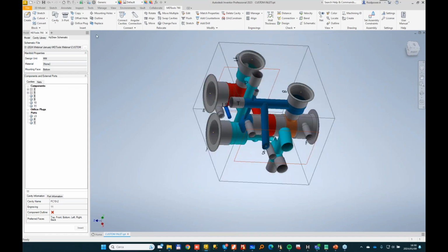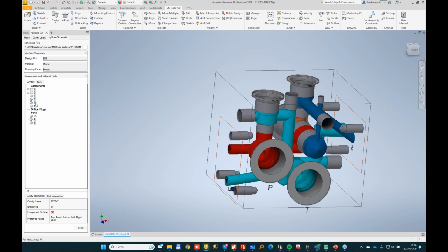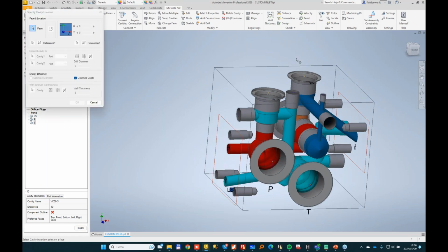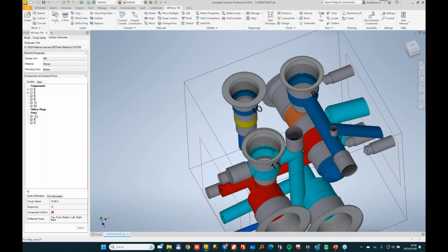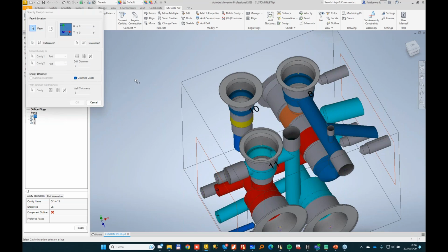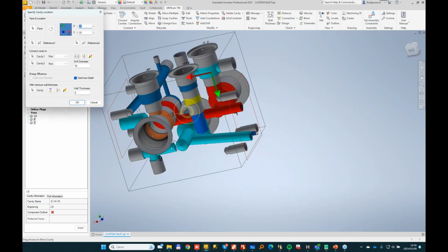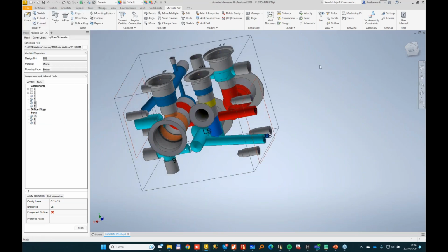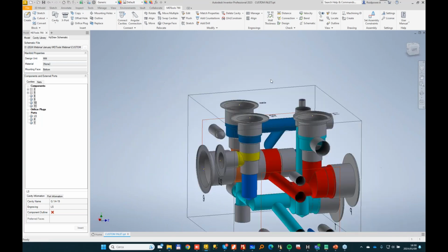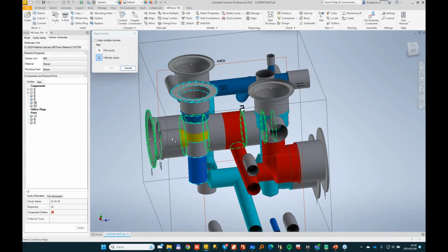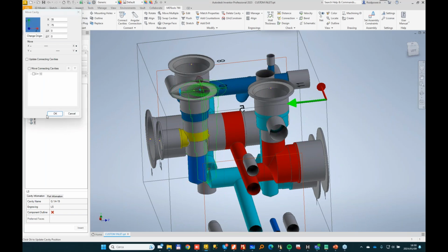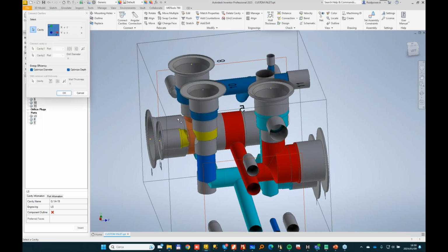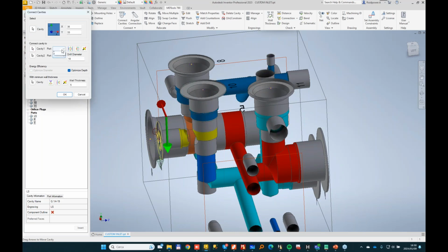So that's good. I need the LS, so I'll put my shuttle valve, and I'll put my LS port, which will be maybe on the back face. I can align these two cavities. I'll need to move slightly my cavity here. I'll connect two ports.